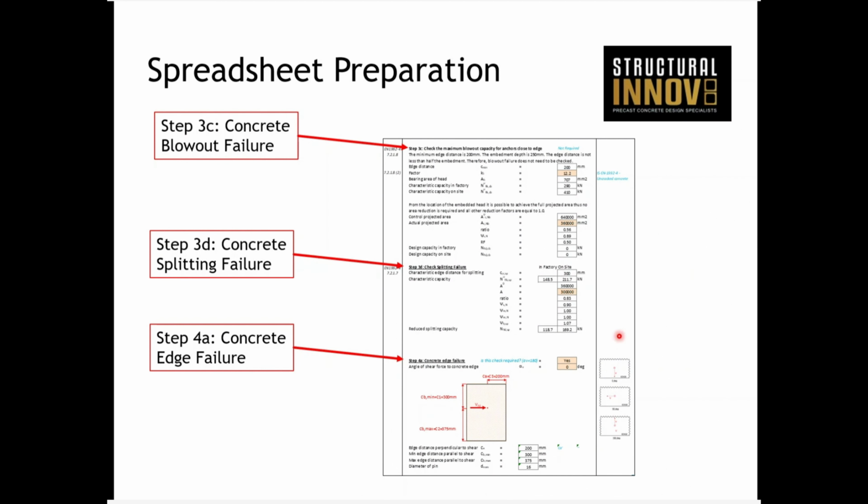So we're down at this stage now. You've calculated the loads in the anchor, you've selected an anchor, and then you've taken that through all the tension checks. You could add in, if you wanted, more visual checks at each step along the way, or you can save it all for the summary table at the end. Either way is good, but the summary table is probably the most valuable because you can see what is happening all on half a page.